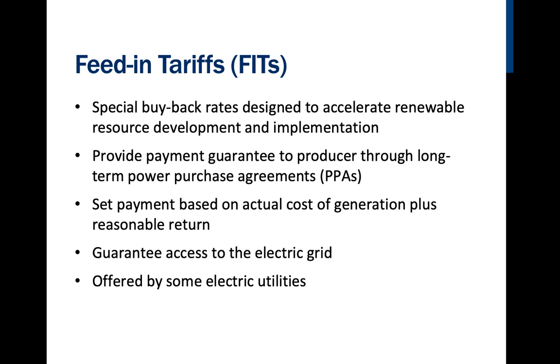Feed-in tariffs. On occasion, there are additional payments that I can reap by putting renewable energy onto the grid. The utility may buy everything I produce at a premium rate, maybe 25 cents or 30 cents or 20 cents, and then I buy at retail rates. So I'm going to have 2 meters and 2 meter fees: a buy meter that supplies my house, and a sell meter which sells everything I produce out to the grid. These are nice programs if you can get in on them.